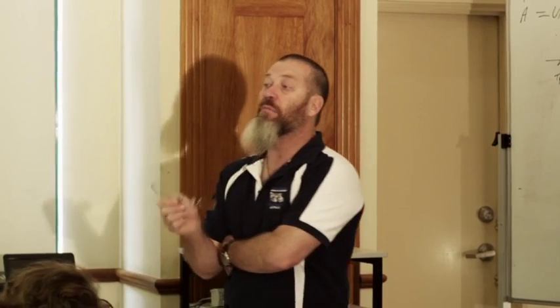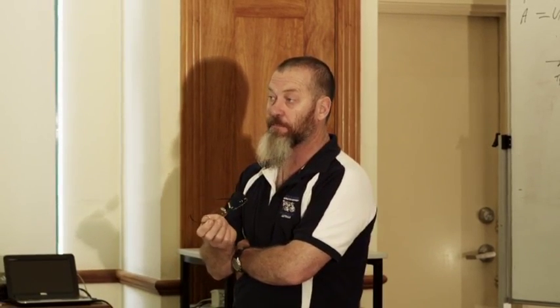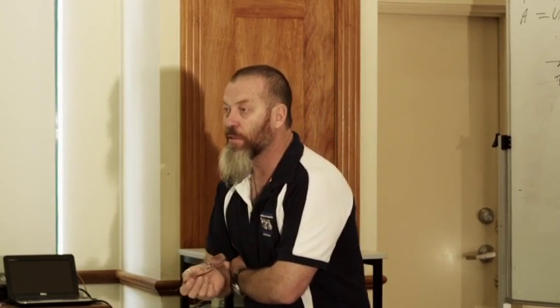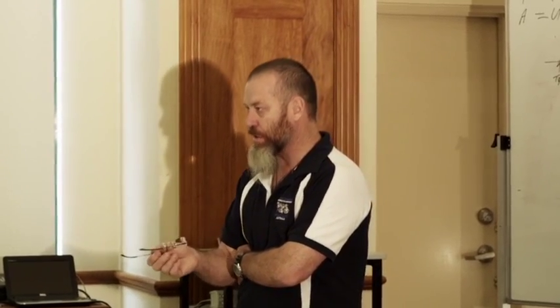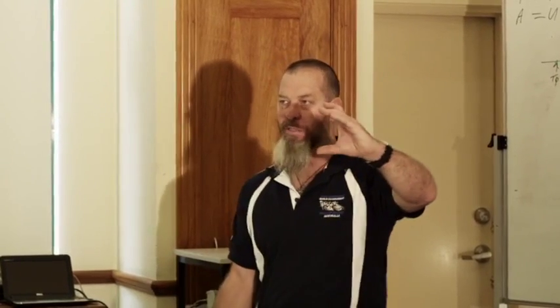Now, I just said to you about the mechanical grading system, MGPs. Computers control MGP systems, not human beings. All your F gradings and everything else is visual stress grading. So they can look at a piece of timber and they can look at the end grain of it and determine whether it's got heart in it or not. A computer can't do that yet. It will get there, believe me. So what we want you guys to assume is that every piece of pine you're going to use, because would I be right in saying the majority use MGP? Okay, as your framing, assume it's got heart in it.